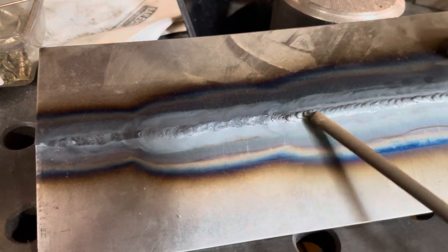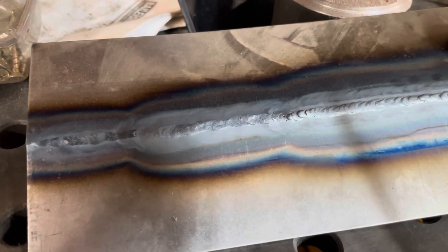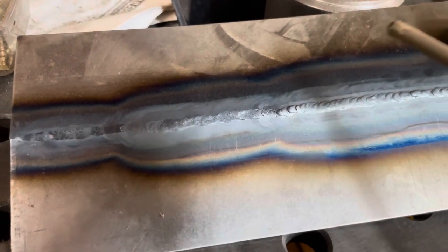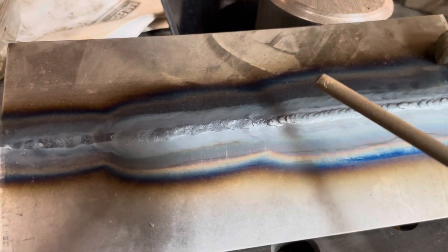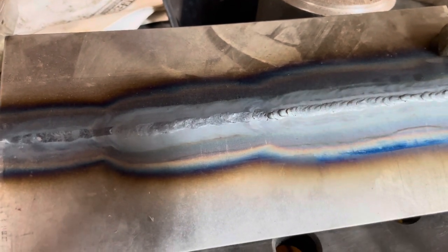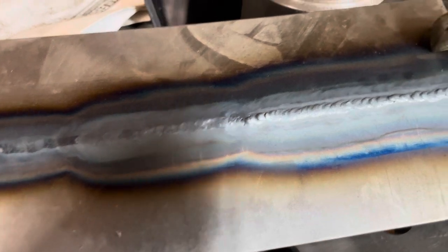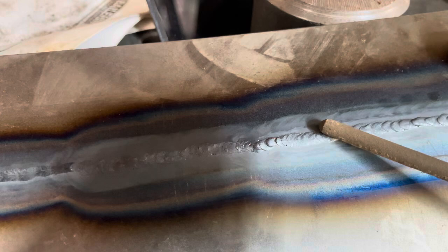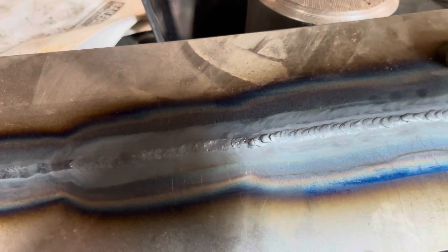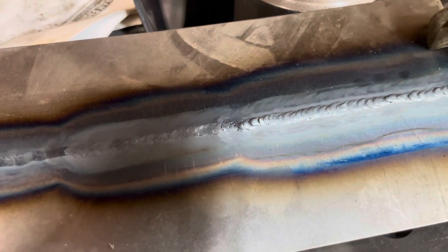Here, I switched to the much larger filler wire. And that much larger filler wire, you can see I had to take even more time to allow that puddle to transition with the heat of that new filler. And that filler was cooling the puddle, so I had to take more time. That time added to the amount of time that thermal conductivity could take over.